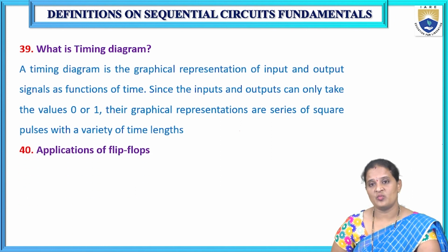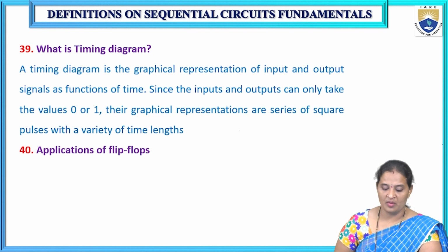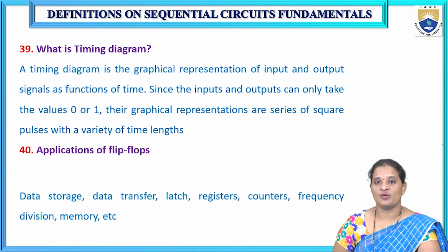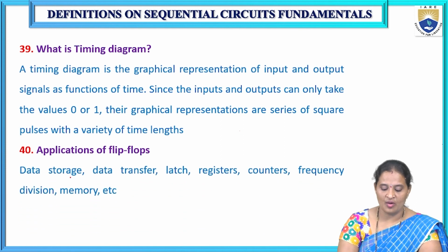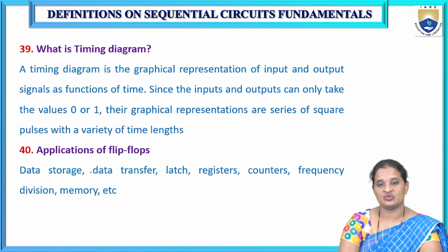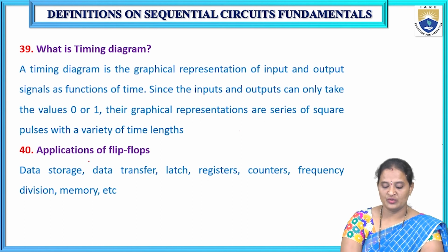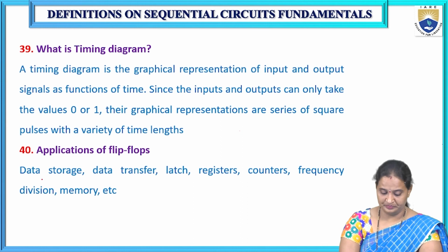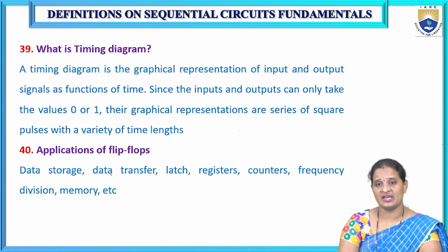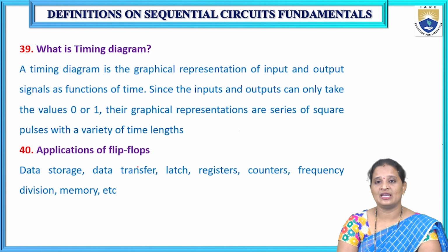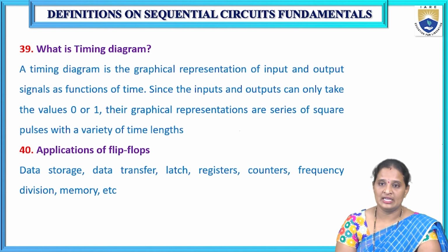We can find many applications for flip-flops, and I will be discussing a few of them. What are the applications of flip-flops? They can be used for data storage, either a single bit or multiple bits. So we can use them as a data storage device, and they can be used for data transfer. In order to transfer data from one place to another, we can also use a D flip-flop, where it can provide the required amount of delay.